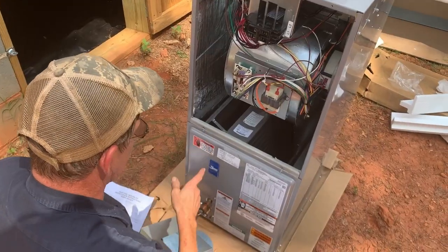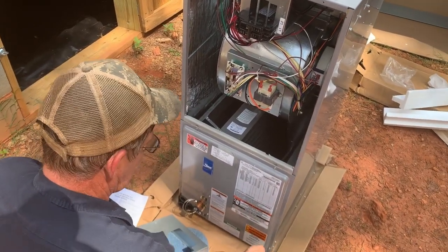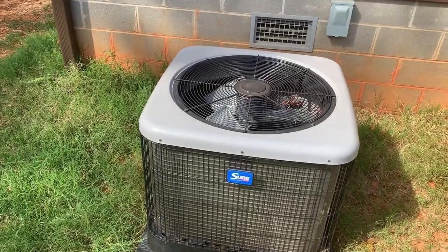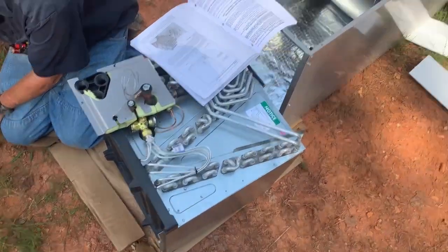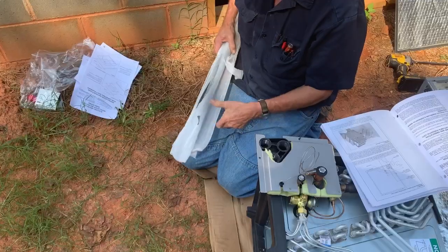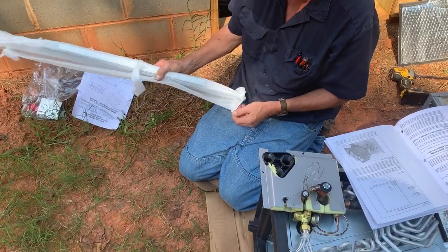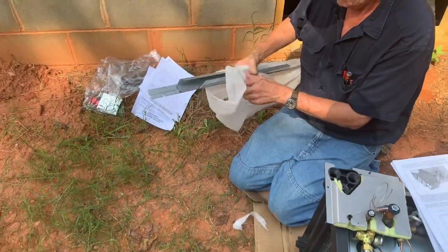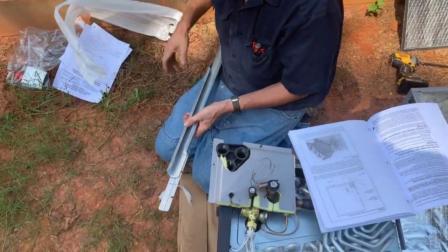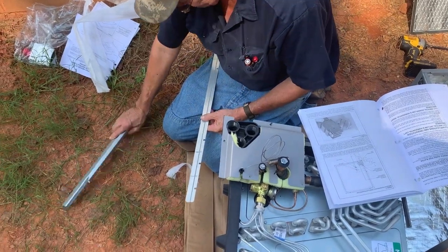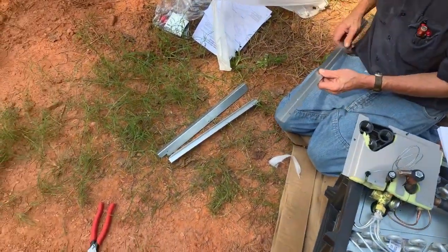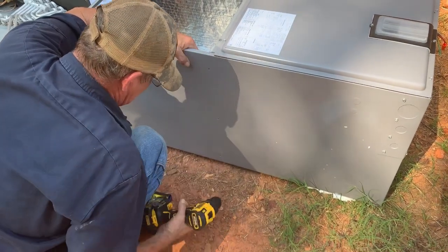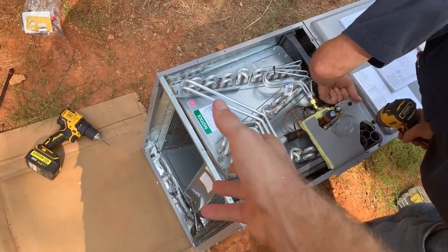I have to change the coil because I want the drain pan on this side, and put that auxiliary heat coil in there. Then we flipped the coil on the indoor unit around so the drain pan faces the other way, because it comes factory one way, but I need it right side down. It has brackets. You drill holes through the unit, mount the brackets in there, and then you can slide the coil down in the slots.